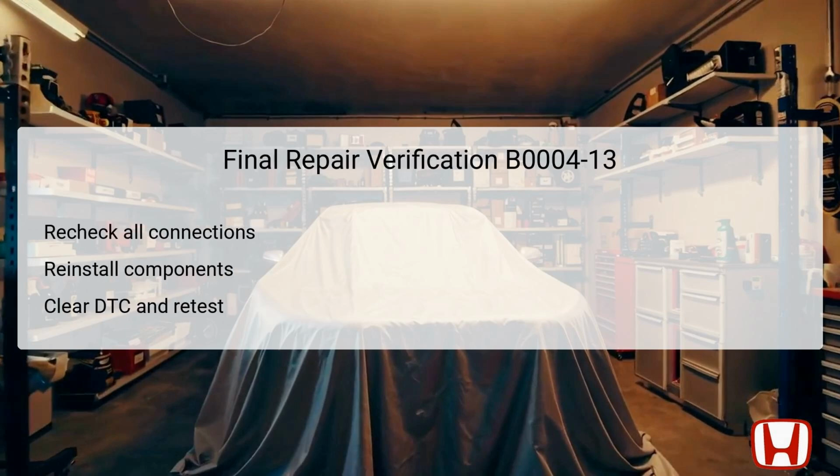After completing the troubleshooting procedure, it is crucial to conduct a final repair verification to ensure everything is in order. This involves carefully rechecking every connection made during the diagnostic process to confirm that they are secure and correctly installed. Any components that were removed should be reinstalled, making sure that they are seated correctly to prevent any recurrence of the issue. After confirming that everything is back in place, you should clear the DTC from the SRS unit.